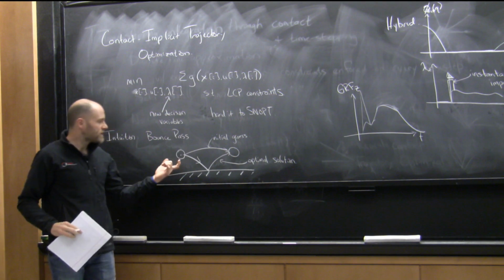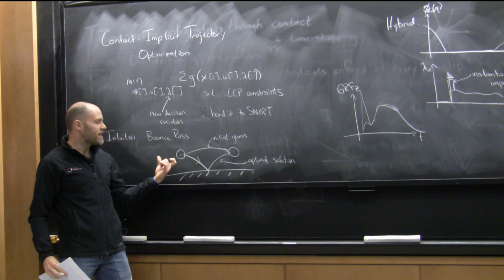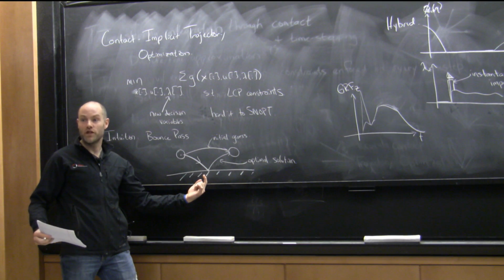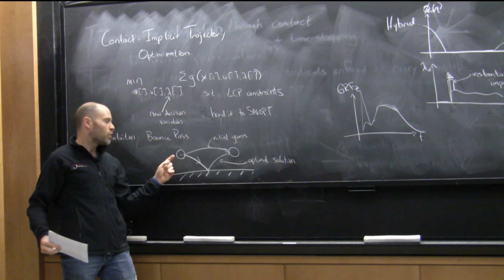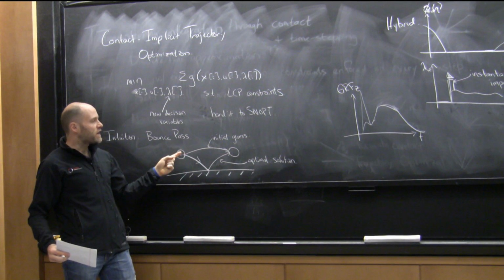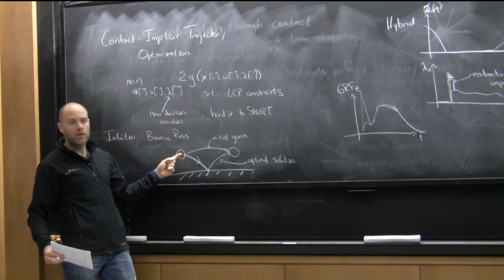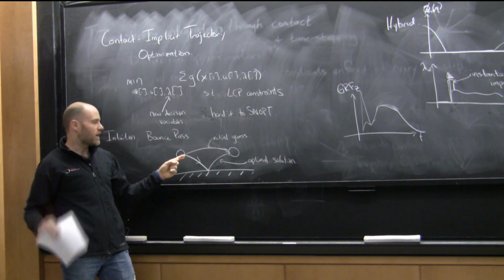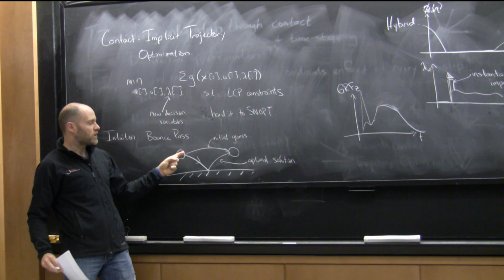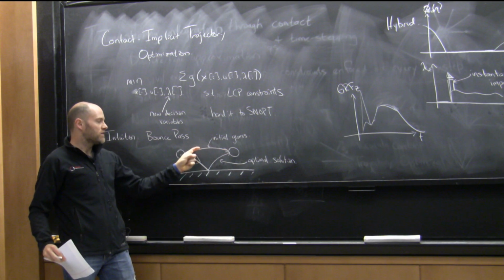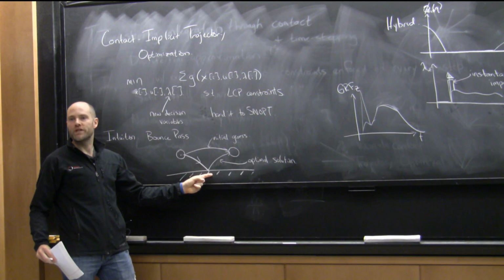So the question is, does the solver have any hope of realizing that there's another, very different solution nearby that it could take when its initial guess is here? If your decision variables are only x and u, then you could use the same sort of time-stepping dynamics to update everything, but it would have no idea that there's this very different thing that happens over here.